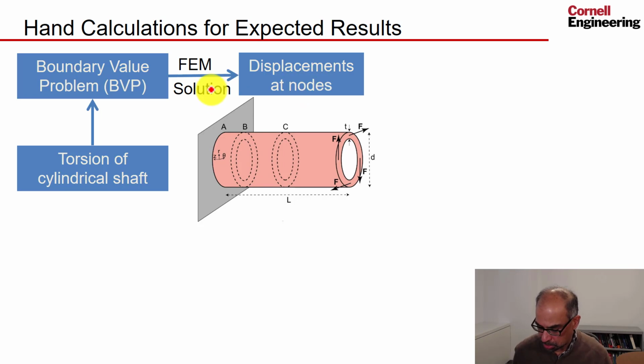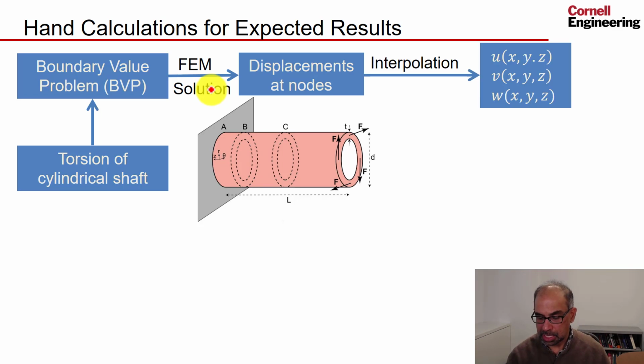And we saw what are the errors introduced in that process. And then once we have displacements at the nodes, we can interpolate those displacements and get the displacements everywhere. And the interpolation happens element by element, and so once we have the displacement field, element by element, we can construct the strains and the stresses.